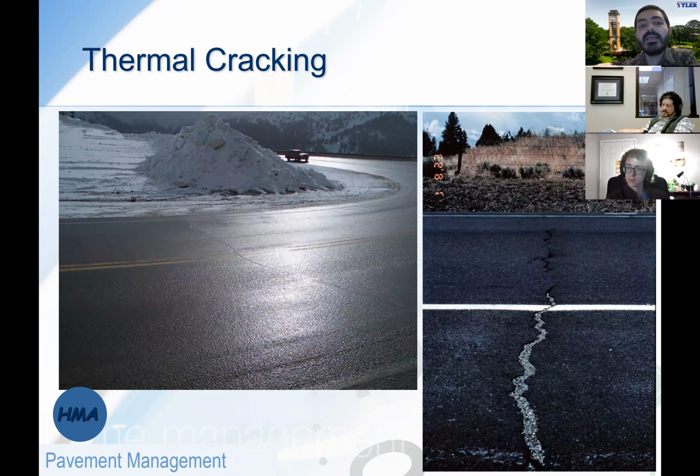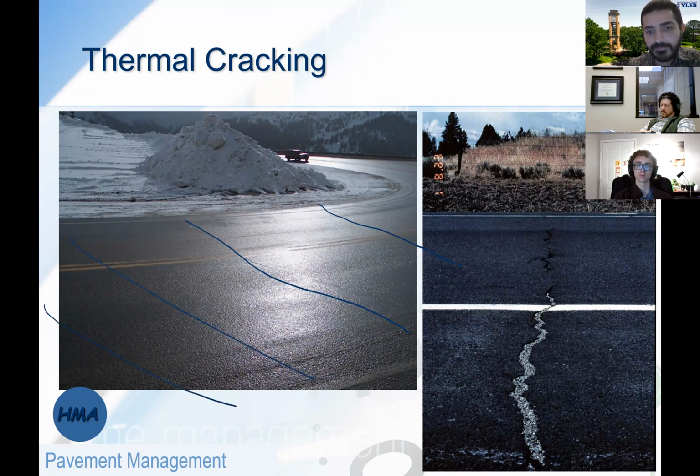It's basically 90 degrees to the travel direction. That's what we call transverse crack. Sometimes we call it transverse crack, and sometimes we call it thermal cracking. And they typically are very repetitive in nature. If you are just driving and you hear that effect of boom, boom, boom, boom every 10 or 15 feet, very repetitive, exactly the same style, this is what we call thermal cracking. So to distinguish it in the field, it keeps repeating very regularly.